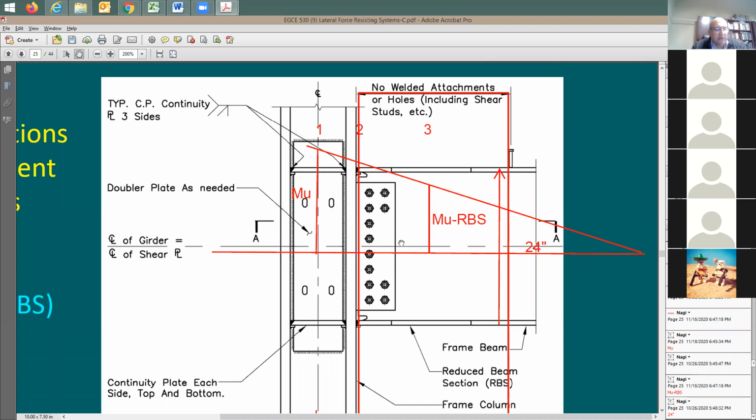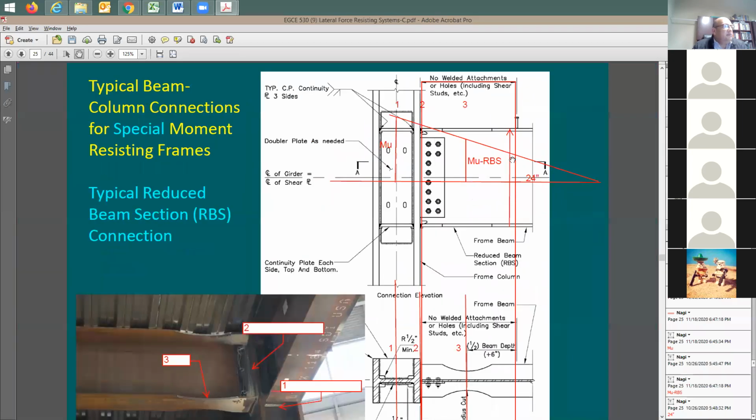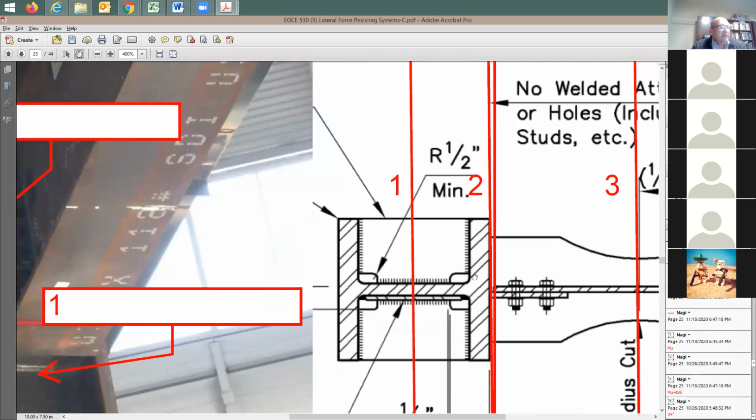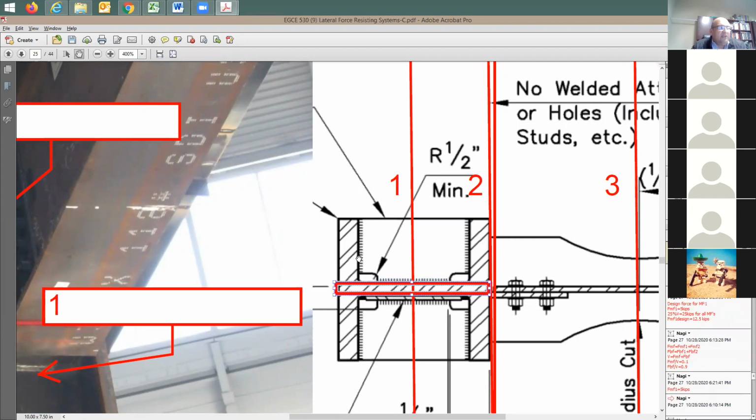Most of the force, let's say that you have a beam, and you have a web. Let's say this is a section in a steel section. A steel section is going to be composed of two flanges and a web. So when it comes to the shear strength, we say it's going to be resisted by the web, correct? How about the flanges? They don't resist much shear.